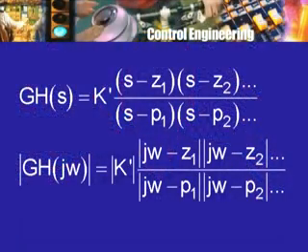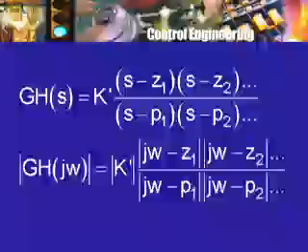All right then. So what does this mean? This means that the dB gain corresponding to G(j omega), that is the dB gain in which we are interested, is given by a sum of the dB gain of K prime, or the modulus of that, plus the dB gains corresponding to these factors in the numerator, namely the 0 factors, minus the dB gains corresponding to the denominator factors.